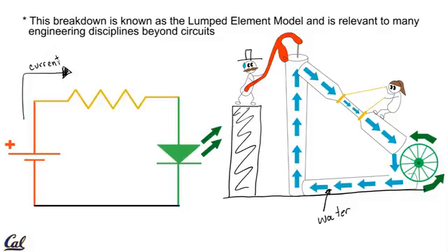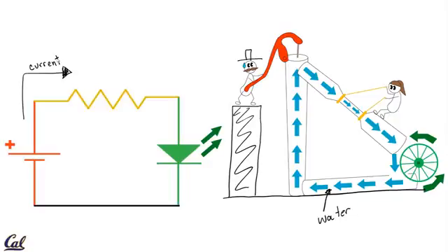Yeah, it's true. Ben Franklin set us down the wrong path, in part because it wasn't appreciated that in metallic conductors, it's electrons that actually move around. What's actually happening physically in the circuits is that negatively charged electrons, which are loosely associated with the metal atoms, are the actual things that get pushed down the wires. So what's physically happening is that negative electrons are going in the direction opposite to those blue arrows we're labeling in the circuit. But for the purposes of circuit analysis, we continue to maintain this fiction, in a sense, that it's positive charge that's moving. As long as you keep that in mind, and I'll label both for this first video so you can see what's physically going on and also our current labels, you should be fine.